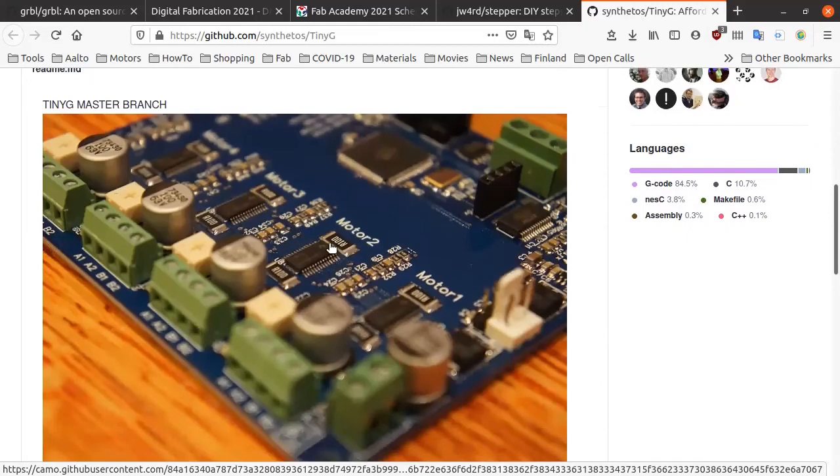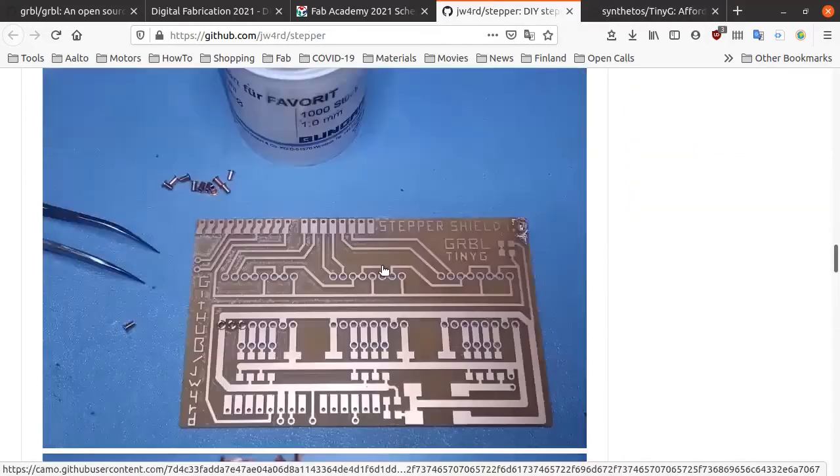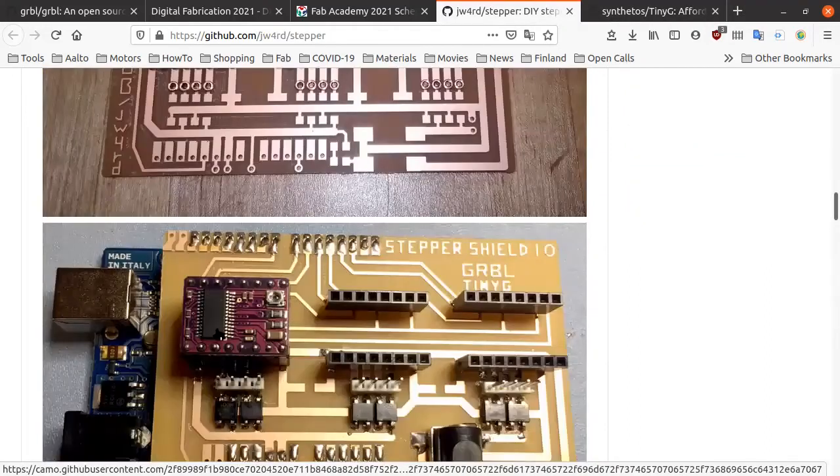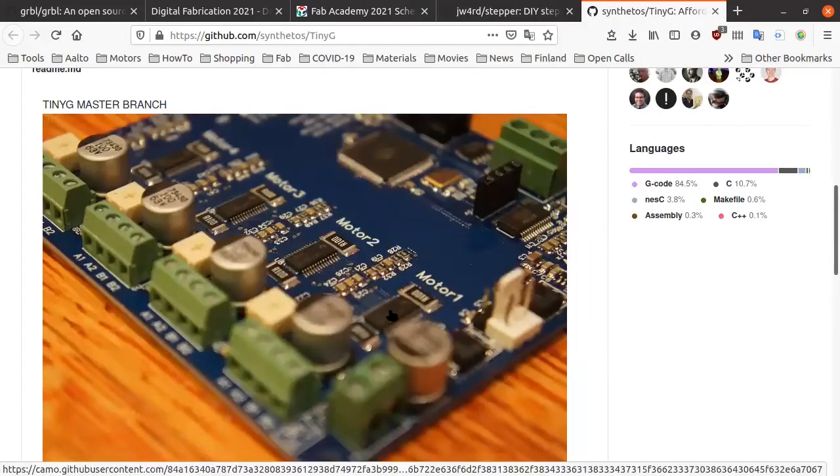So it's less flexible than this one, for example, because with these step sticks, whenever a new stepper driver comes out, somebody might create a step stick, or you yourself, and you could just plug in a better stepper driver in the existing solution instead of ordering a new board where you need to resolder these chips, so to say, risking to damage your board.